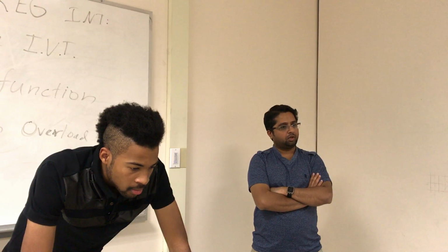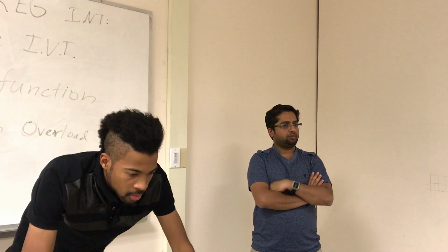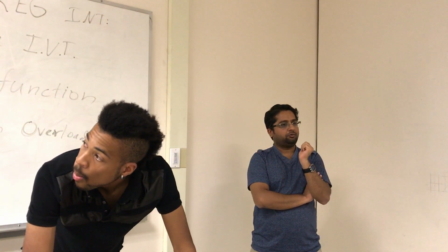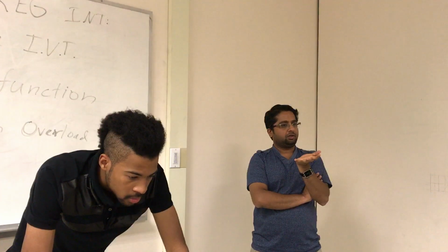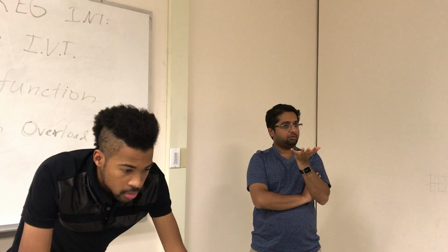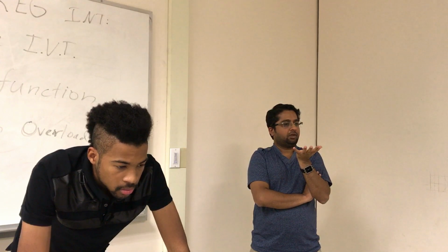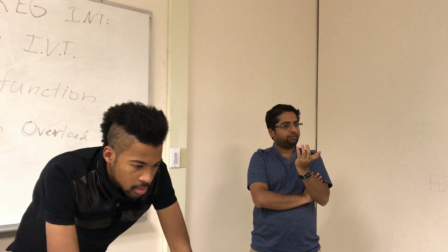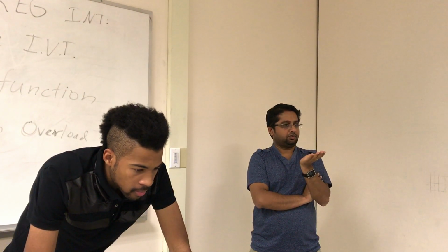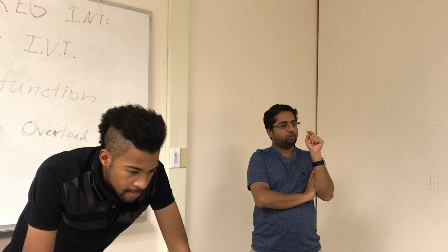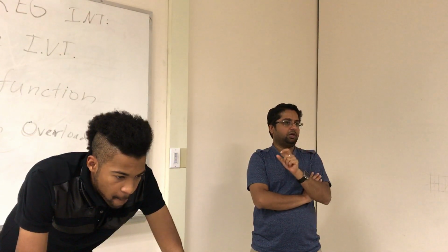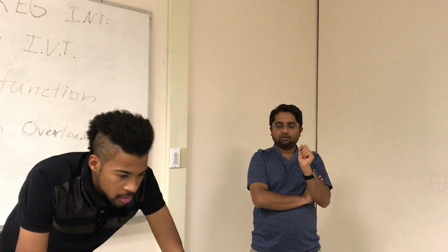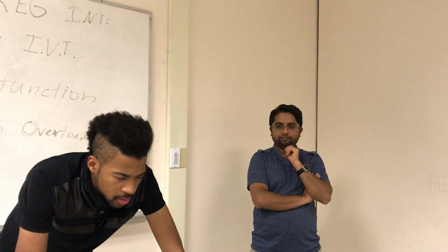what we did for lab 1 was configure a pin to set it high and set it low, right? So this time what you will be doing is, for one of the GPIO pins, you will be configuring it as input because it needs to send something, and then you will be setting up the rising edge and falling edge register to actually react to those edges. So you will be setting the registers for the rising and falling edge. Basically, it's section 9.5.